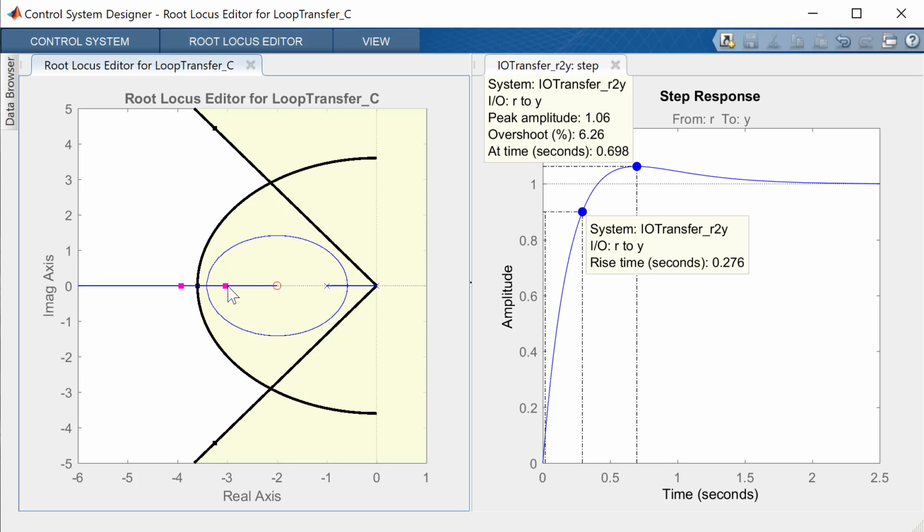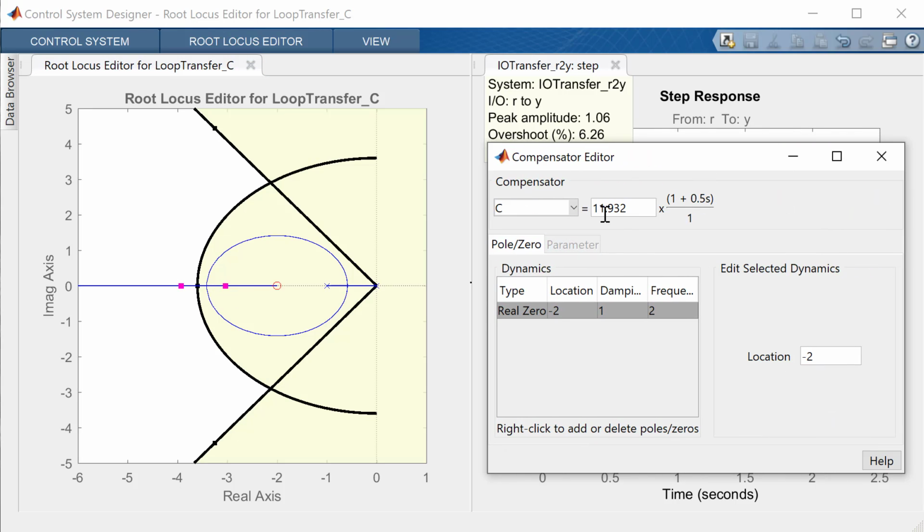And so it leads to a very stiff system. You can imagine that's similar to spring constants that are extremely stiff. And so those end up with very harsh control laws. So in general, we try to steer towards controllers that lead to smaller inputs, and a small gain is a good way to ensure that. So there are ways to achieve this, but we are using a relatively large gain. In this case, it's about 12.